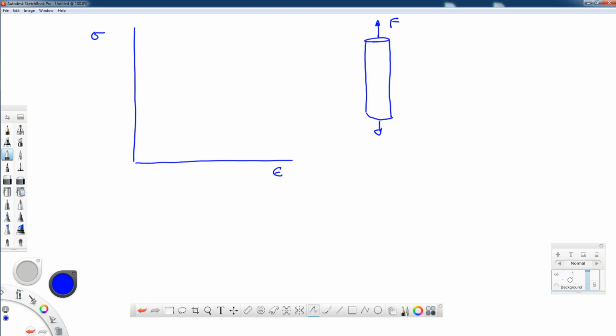Let's talk just a little bit about how a tension test is typically conducted. We take a bar that has a certain gauge section that I've drawn here on the right side of my picture, and attached to this is an extensometer. It's a little electrical device with some wires that go off, and it measures the extension of an initial gauge length. So the L0 may be an initial gauge length, and it gives an electrical signal that's proportional to the change in that gauge length.